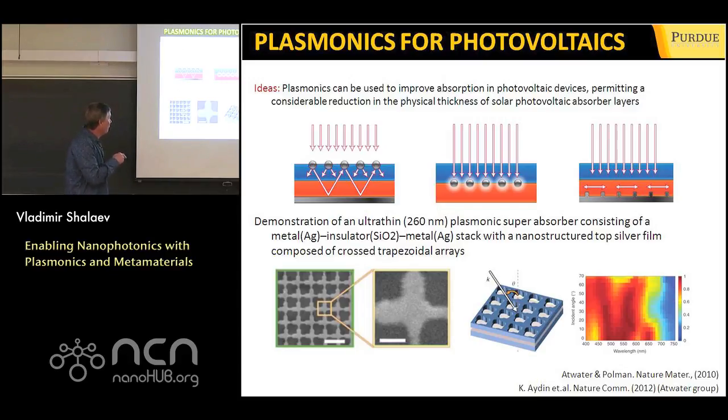By introducing these particles, you make this broad angle scattering. So large angle broadband scattering. And because of that, you effectively increase the propagation length for photons. One of the biggest problems for photovoltaic cells is the photon mean free path. It's much larger than the charge carrier mean free path, meaning that you do not absorb photons on the scale where your charge carriers propagate. So that's why you don't have enough efficiency.